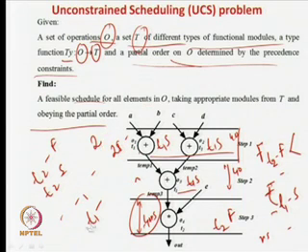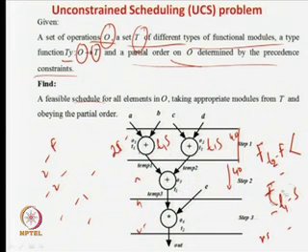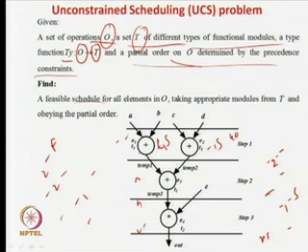So, what I am finding out is that this is the slowest guy. So, even if I do my best effort, even if I am using type 2 fast, this is still about 40 nanoseconds, and I cannot bring it below that. Then I will take such types of adders which will get me my answer in less than 40 nanoseconds and take the minimum amount of power and area.